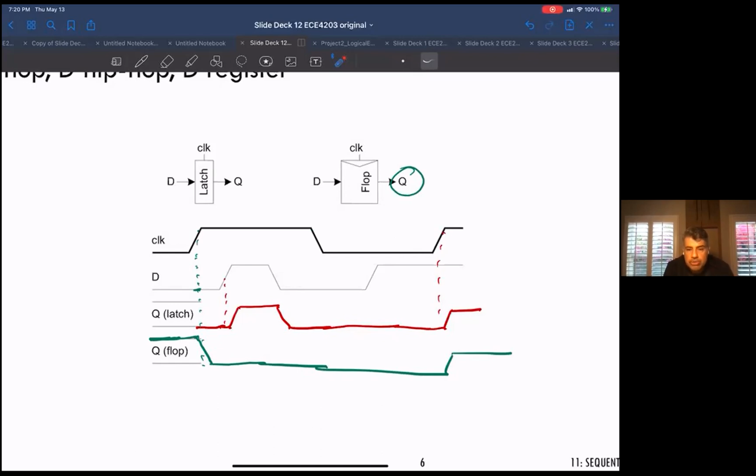These place and route tools understand flip-flops, and they understand them very well. In terms of the timing constraints, they can deal well with edges and flip-flops. I don't know why. Probably for the same reason as I mentioned, there's only one point in time they have to worry about whether stuff gets there or not. They don't understand latches well. So they will screw up latches, every time.